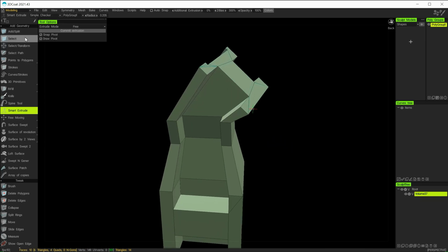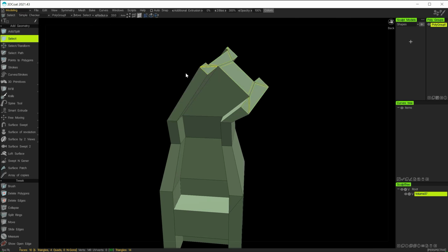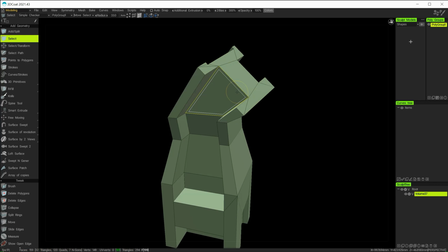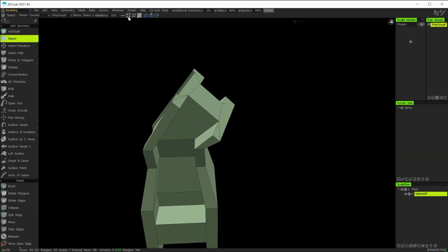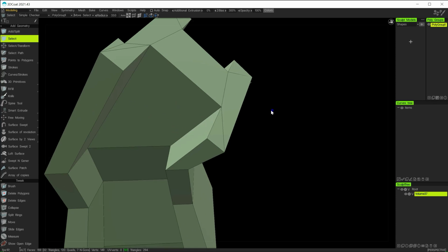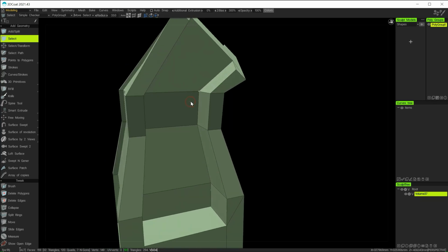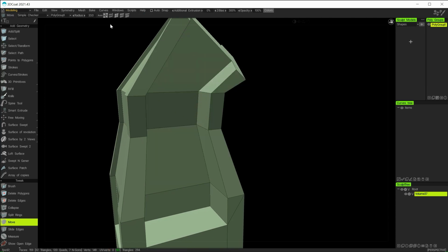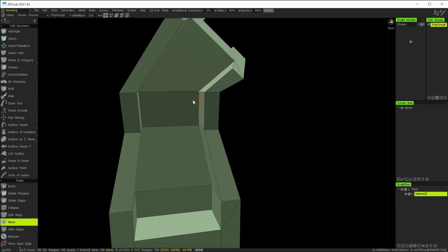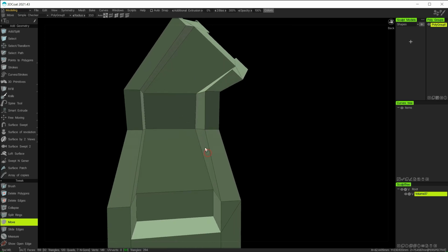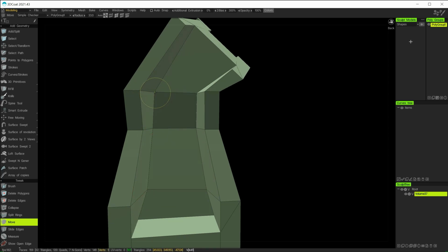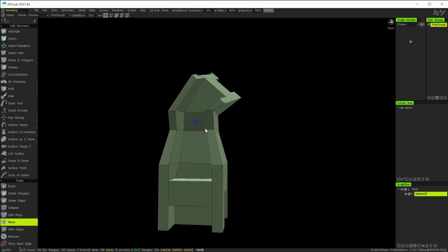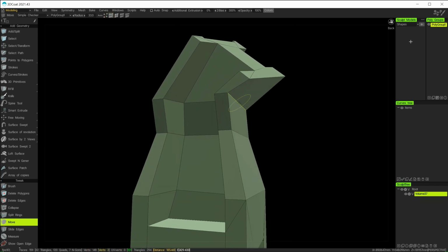So at this point I will just deselect all these objects by hitting Control D, and I'll go back to the points selection here, and I can start to modify this geometry on a points basis. So hit space on the keyboard, select move. So I've got verts selected and I'm moving those verts around. You can see that I can now start to shape this model. And I can just sort of tweak it using edges or faces.